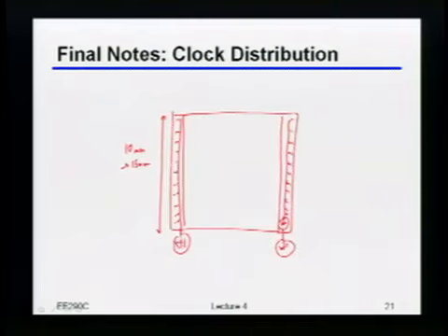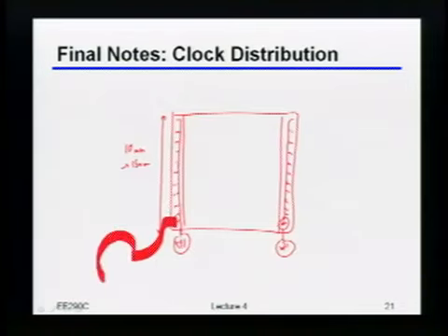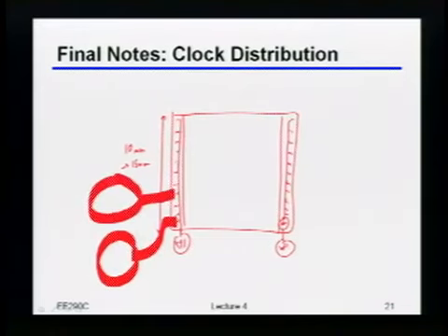There's also, of course, another trade-off, which is how much power it takes to actually distribute that clock. From that standpoint, doing something at the lower frequency seems more attractive, because there's lower loss there and you pay lower CV squared F just because you have a lower frequency. But of course that means that locally, and I'll draw it over here on the side, each one of those tap points would have to multiply that clock frequency up to get to the very high frequency you need on the actual line rate itself.